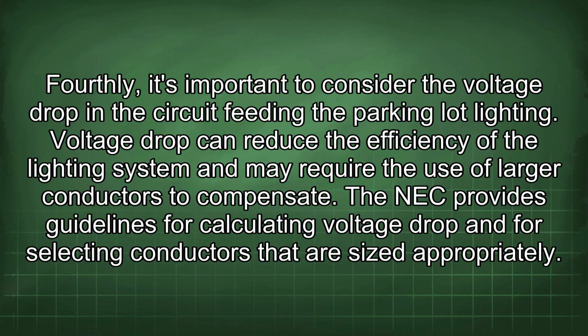Fourthly, it's important to consider the voltage drop in the circuit feeding the parking lot lighting. Voltage drop can reduce the efficiency of the lighting system and may require the use of larger conductors to compensate. The NEC provides guidelines for calculating voltage drop and for selecting conductors that are sized appropriately.